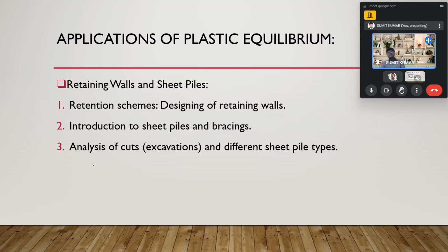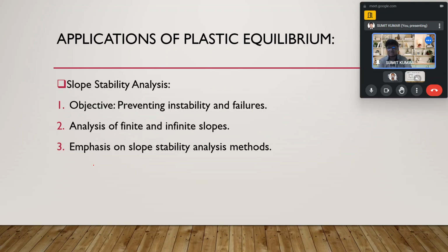Because anytime we are studying the sheet pile wall, or any retaining wall, as you go from one place to another, you have seen beside the road the very large retaining walls. On those retaining walls the plastic equilibrium application is applied. Those retaining walls take the aspects of the active and passive earth pressure, so that understanding needs to be very clear for the designing of the retaining wall.